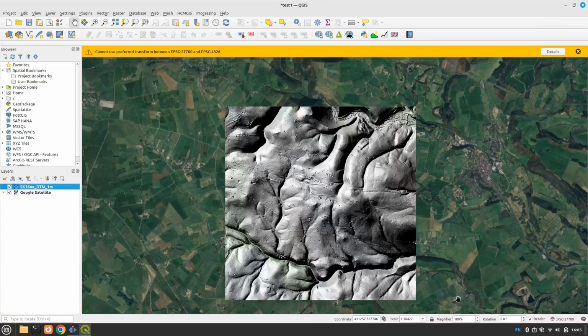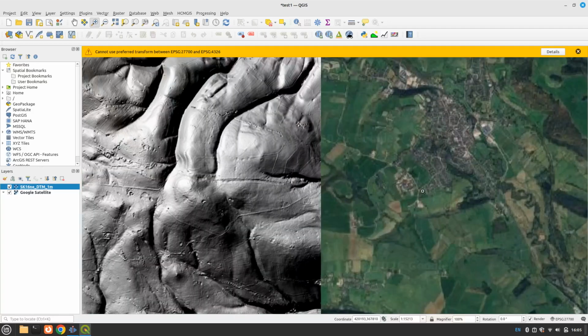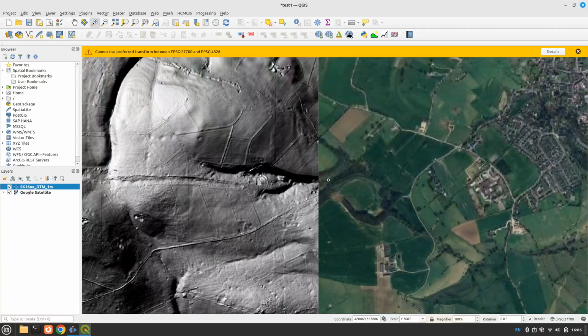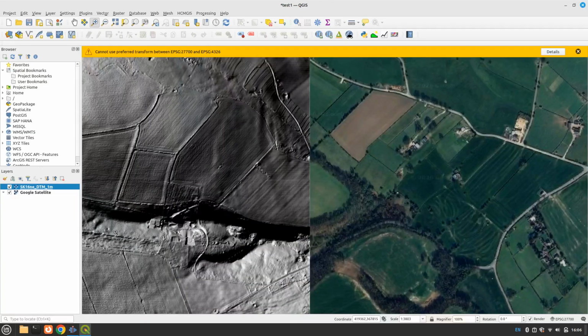You will notice that when you zoom in, all the rows line up with the underlying imagery, and the landscape looks to be where it should be. The LiDAR tile has positioned itself exactly where it should geographically. This is because we set up the CRS correctly, and the LiDAR tile knows where to locate itself when we introduce it as a layer. If you get the CRS number wrong, then this is where it becomes obvious and the layers don't match up.